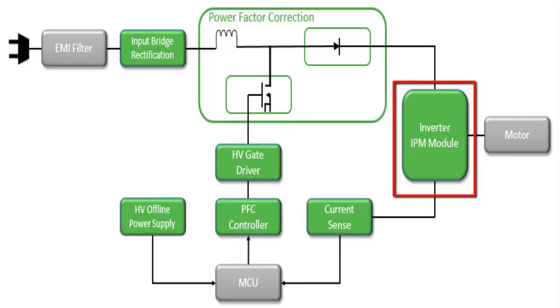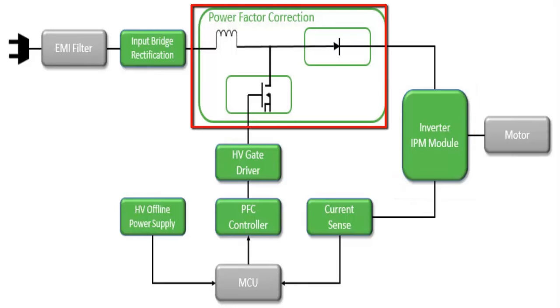It is advisable to focus on the IPM circuit, which distributes this generated voltage. If no LED lights up, consider reviewing the PFC circuit, the voltage generator.